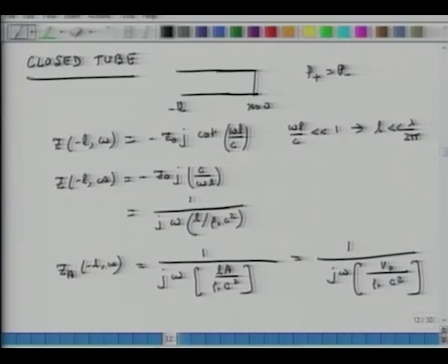When we look at the physics of this tube, as we saw in earlier lectures, pressure will be maximum here at the closed end. Whenever you have a closed wall, pressure is maximum here, and from here it will start falling as I move away. But because L is significantly less than lambda over 2, that fall in pressure will not be significant.